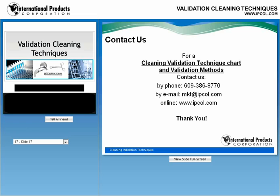There's a question regarding TOC and inline. Do companies use online TOC in their rinsate lines? Most companies that use TOC seem to use them as standalone procedures. In other words, they take a sample, they run it off their line, they run a TOC analysis. I haven't heard of any companies that do them online. I assume that technology is out there, but we haven't come across any that do it online.